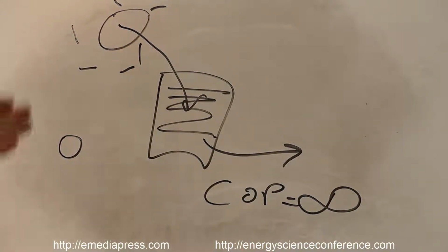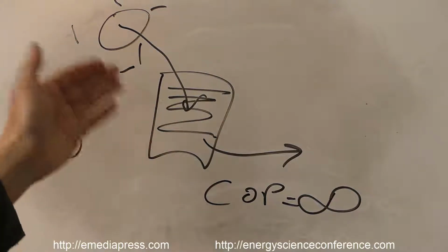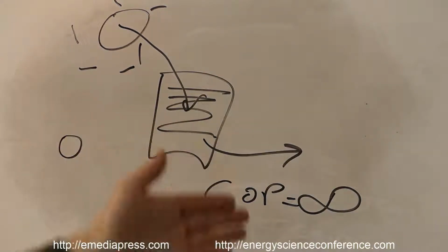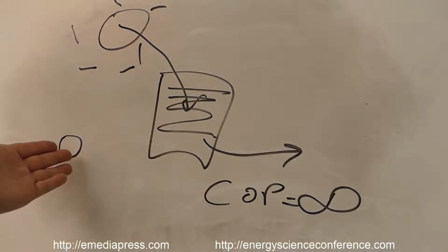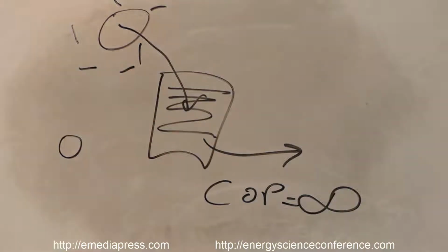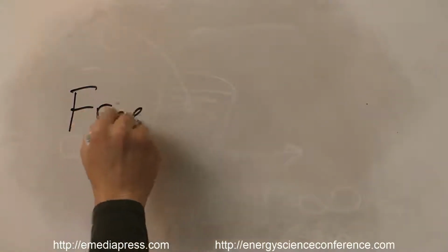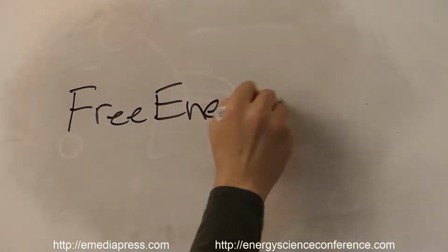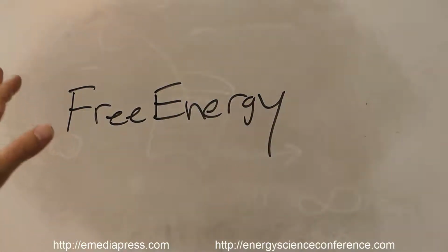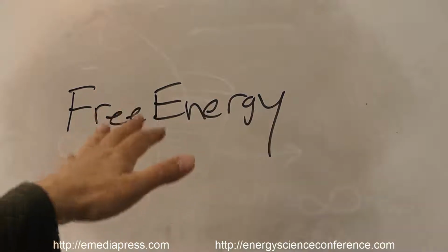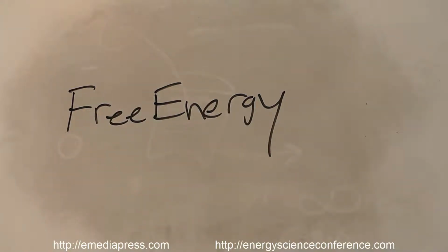Our input is 0, which means the COP is considered to be infinitely more than nothing. And solar power, hydropower, and wind power basically all have COPs that are basically infinite because you don't have to put anything into it. It's all provided free from the environment. The efficiencies are going to be low, like, the common solar panels are going to be in a low 20% range, yet it has an infinite COP because you don't have to put anything in.